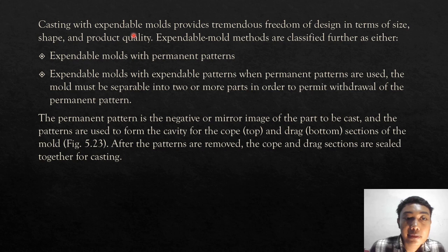Then next, casting with expendable molds provides tremendous freedom of design in terms of size, shape, and production quality. Expendable mold methods are classified further as either expendable mold with a permanent pattern, or expendable mold with an expendable pattern.